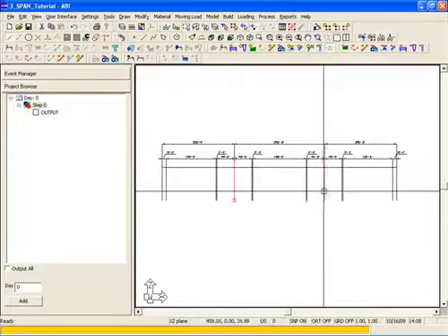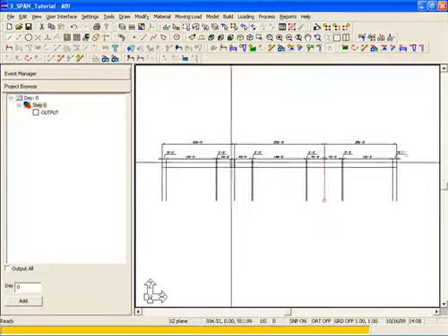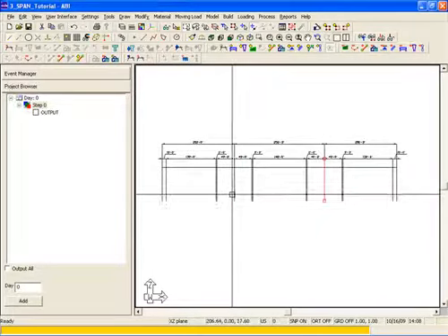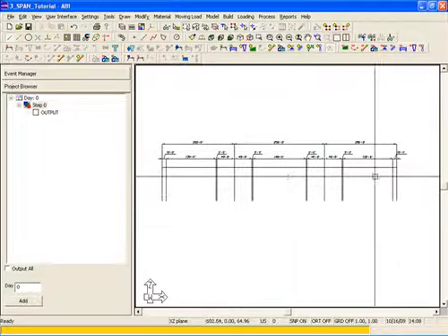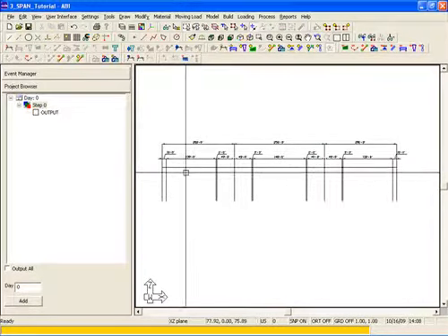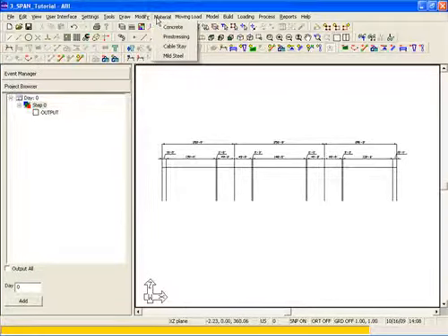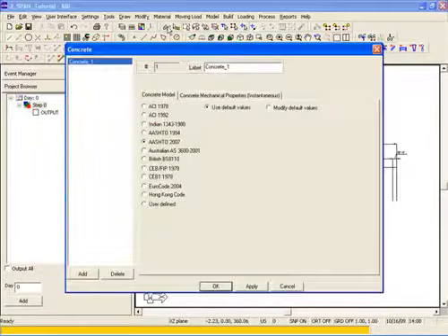The 2 pier lines or pier center lines are here, and the piers will be 50 feet from the top of deck. Prior to beginning modeling of the pier and also the deck sections, we're going to go ahead and validate the material for concrete, pre-stressing, and mild steel. We're going to leave the default values alone for the different mechanical properties and creep and shrinkage values.